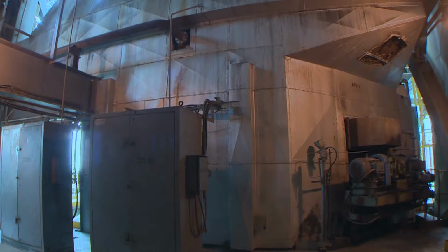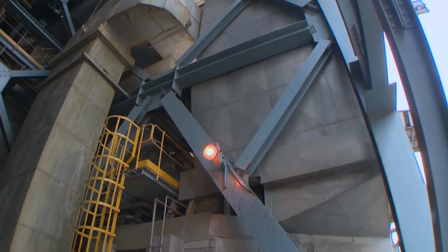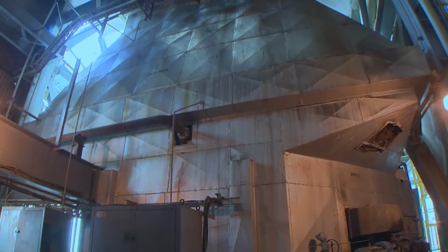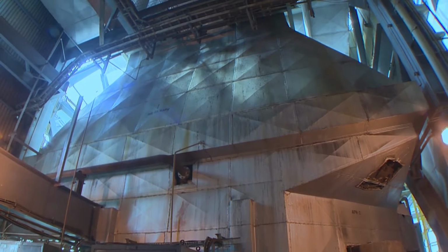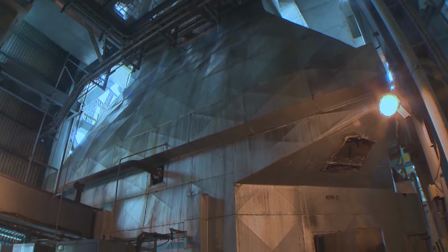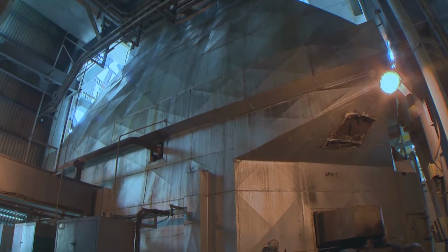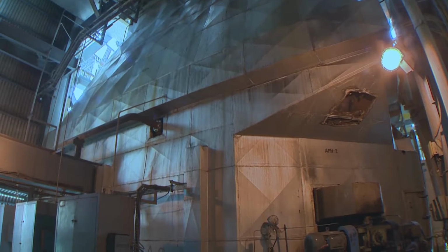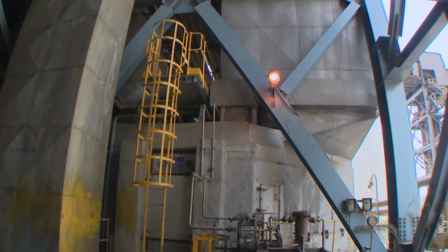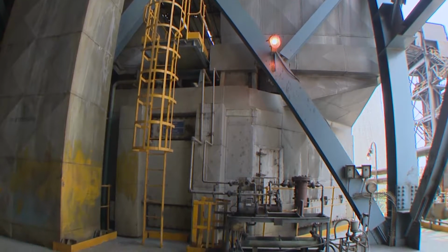Regenerative air preheater. In the bisector type regenerative air preheater, flue gas goes out from furnace through one half. Through the other half, air from forced draft fan comes into the furnace. The air preheater rotates at slow speed, that is 2 rpm, by means of an electric motor. The heat contained in hot flue gas is transferred to the incoming air, thereby increasing the air temperature, and the flue gas temperature is reduced. This helps to increase the boiler efficiency.